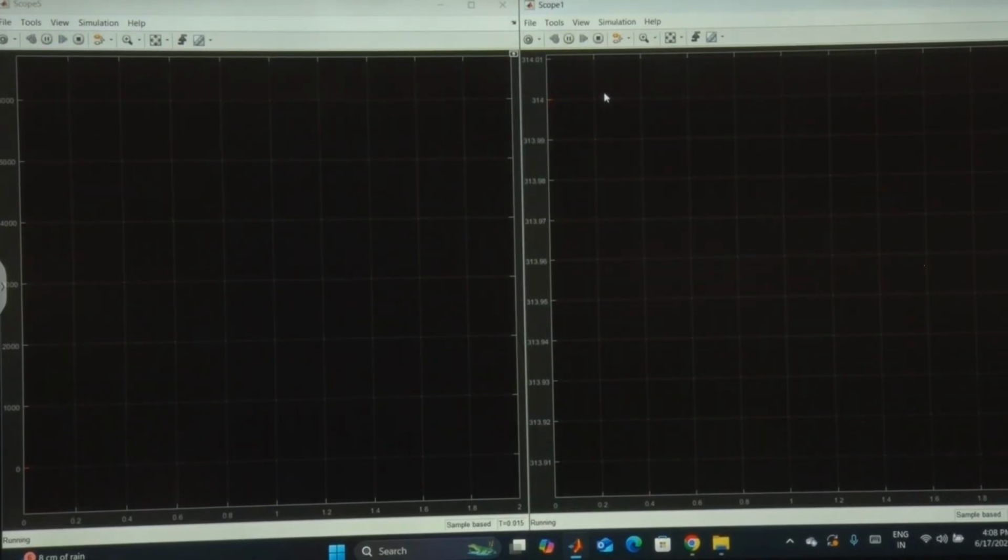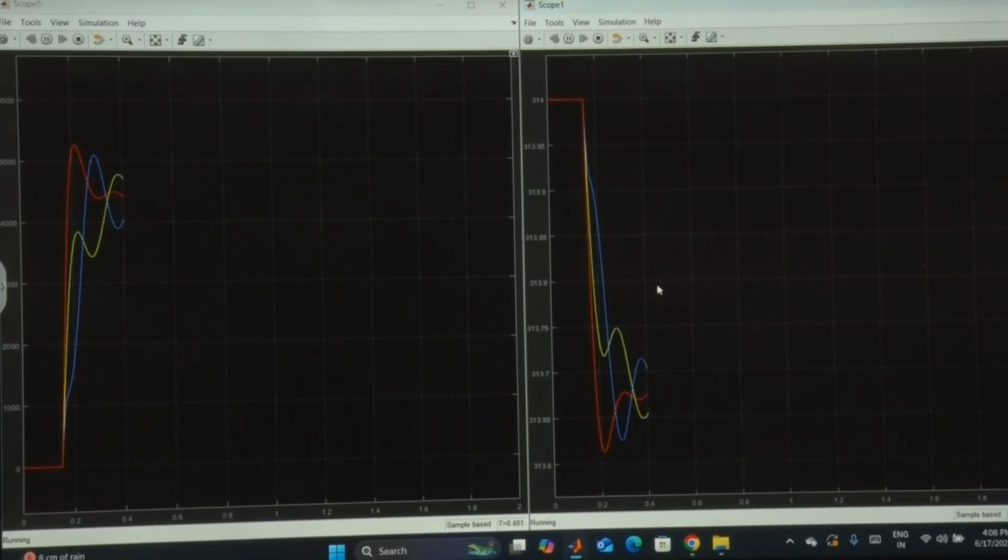now it is becoming steeper, that means the frequency will change quickly. If the frequency changes quickly, the integration of omega 2 minus omega 1 dt, that is the angle, will change in a relatively faster manner. Then your power flow P equal to EV by x sin delta, the change of power becomes quicker. So therefore, others will try to match it very quickly. You can see now it has come down almost to 5,000. But the effect is the frequency has fallen more, so the regulation has become more.